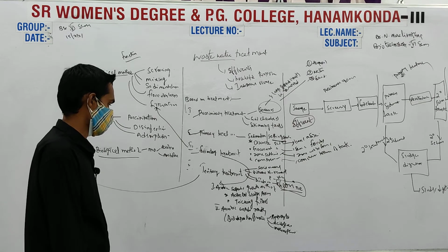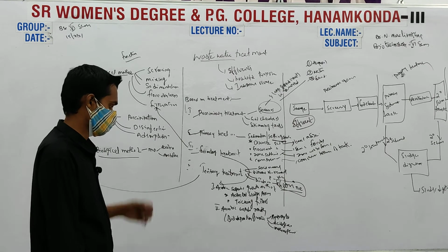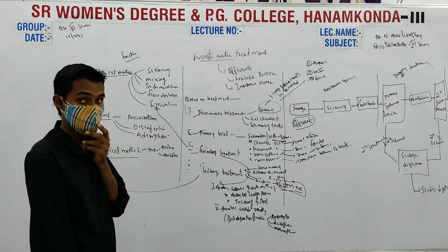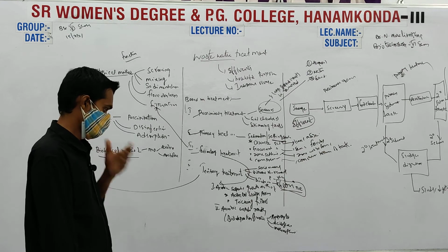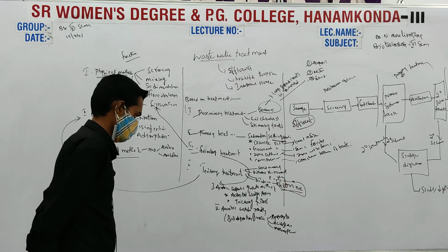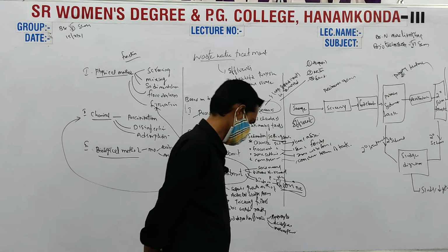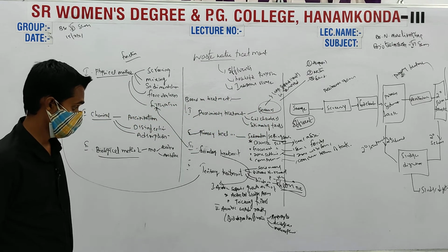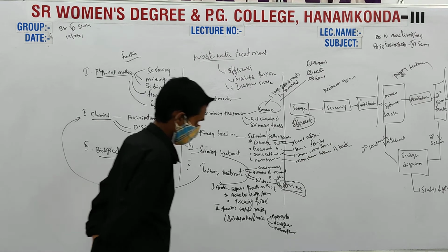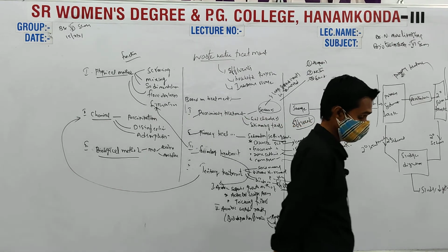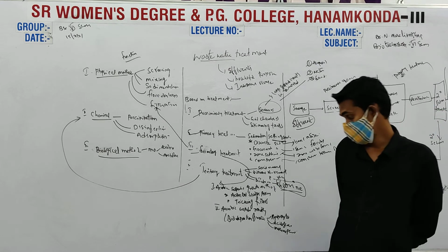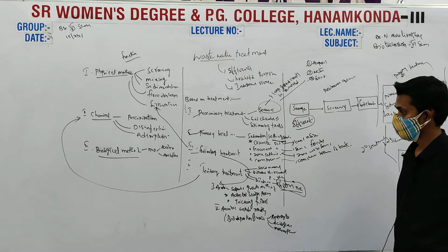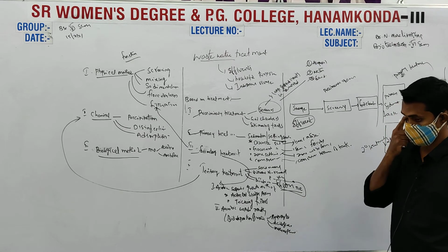And the next method is the anaerobic suspended growth method. Here we use anaerobic conditions for the treatment, which includes biodegradation of waste. It has different steps, that is hydrolysis, acidogenesis and methanogenesis. So this comes under secondary treatment.